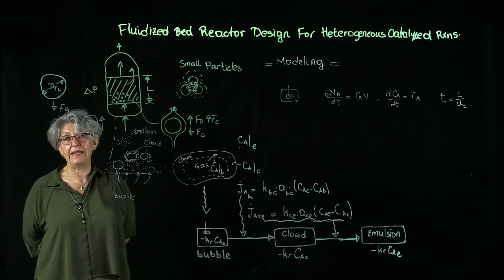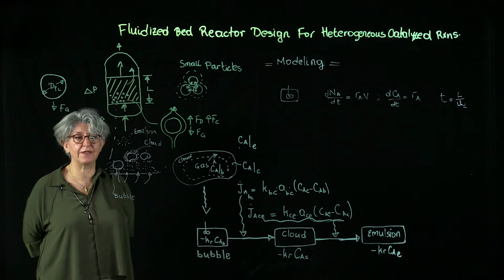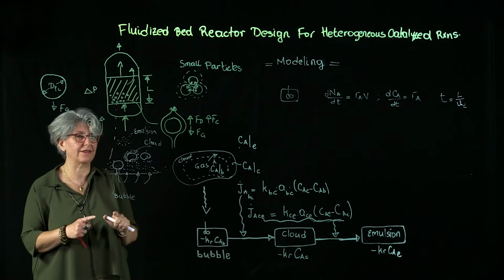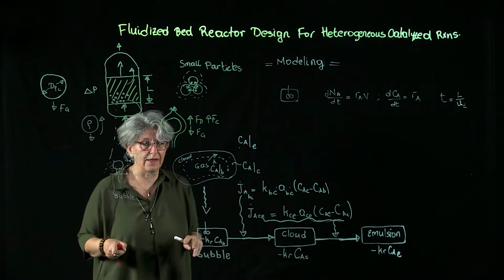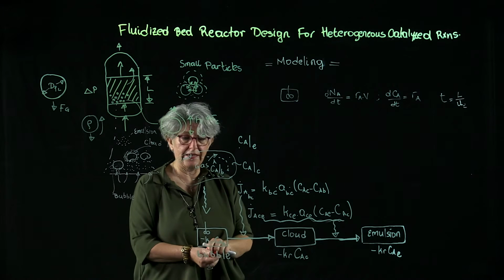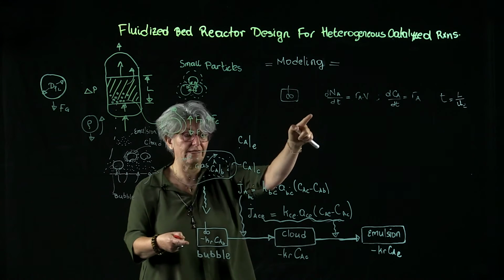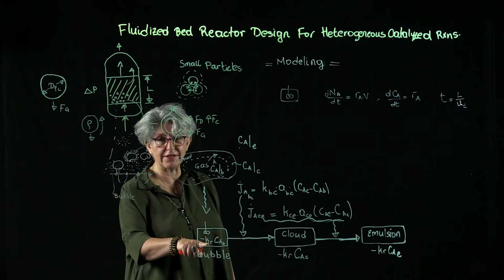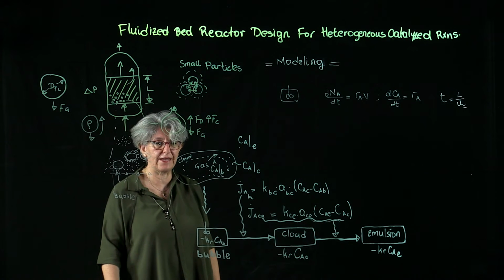where we have a reaction and a mass transfer that is taking place, and we are considering all of that at constant temperature. We haven't introduced the effect of temperature into this problem yet. As I mentioned earlier, we are going to treat the bubble as a batch reactor, where the reaction taking place in that batch is represented by a homogeneous model with a reaction rate constant K and the concentration of species A represented as CA bubble.